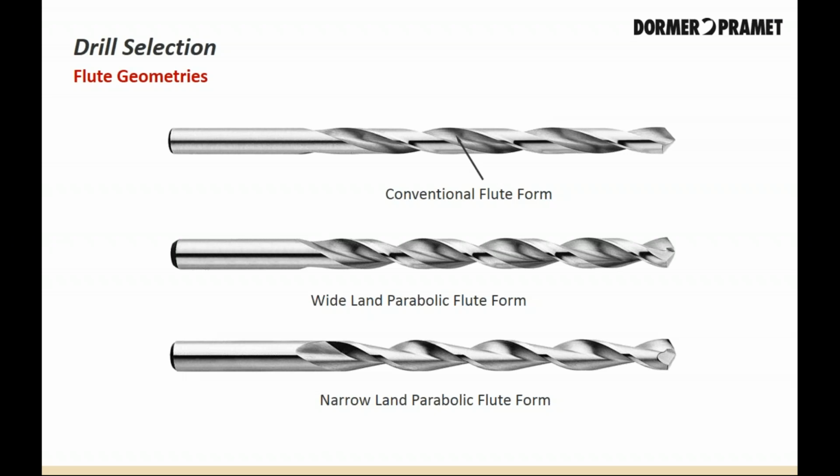Parabolic drills will be best applied where the feed rate can be controlled, so the drill doesn't pull itself into the workpiece too fast.